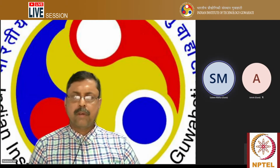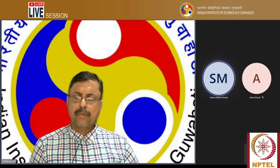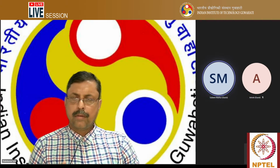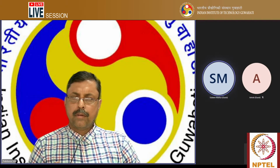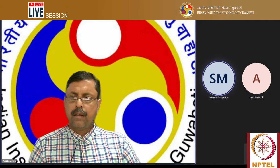Yes. Actually, sir, I tried. I followed some other videos on YouTube, and I found that there is a method to introduce two terms when there are two terms in the numerator side. For that, you have to enter K value equal to 1 and E value equal to 0 in that reaction window, and in the driving force. I didn't get you. Sorry. There's a window there in the reaction kinetics where you enter the reaction kinetics parameters for K and E.